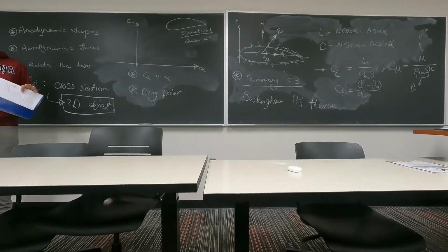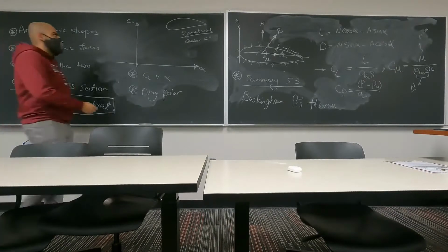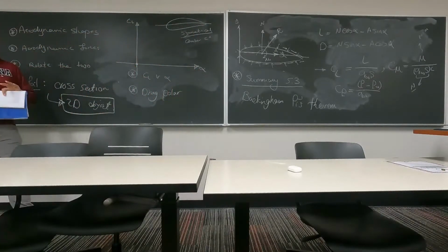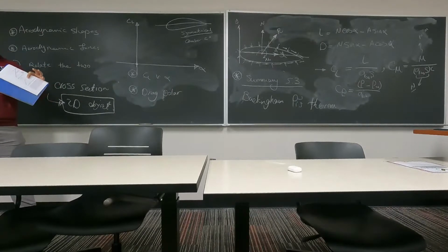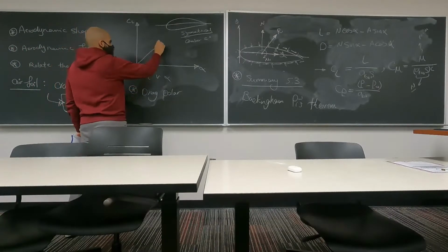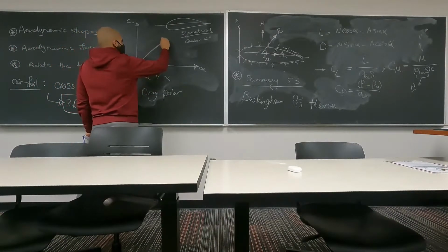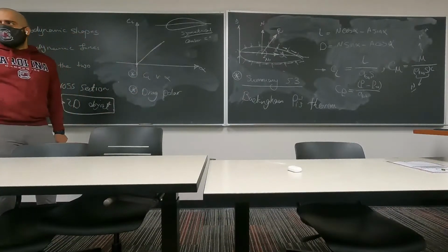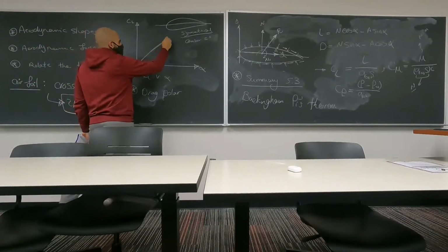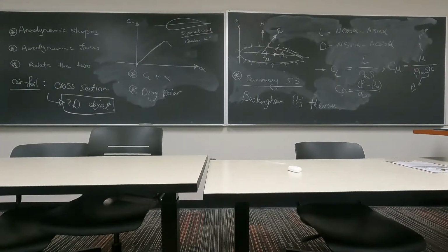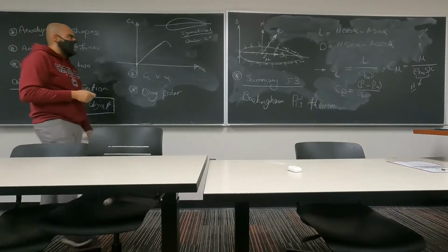The distribution of the flow is very symmetrical over the chord length, right? So there is no pressure difference between the bottom and top of the airfoil. So you're going to get 0 lift, right? And this lift changes linearly until some point, and then we're going to have the stall condition at which we will see a huge reduction in lift coefficient, right? Hopefully we are all familiar with the stall condition and what happens during a stall from aerodynamics. If you haven't passed aerodynamics, you will see more about this in your aerodynamics.